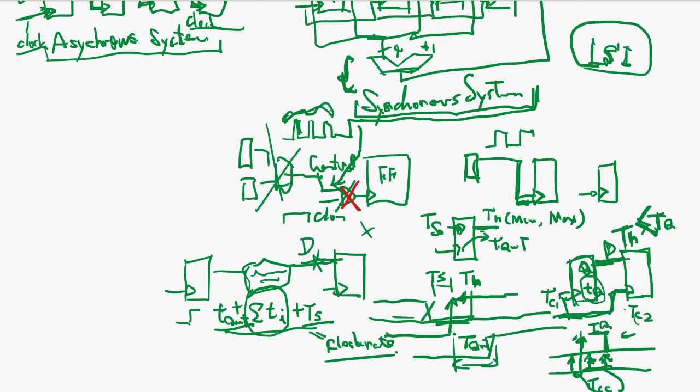If there is a clock timing skew, it may violate the setup time or hold time. In this kind of case, you want to have some kind of artificial delay, so you can insert some logic in order to make sure it satisfies all the conditions. Okay, so you have this kind of logic. You have to be careful when a flip-flop output directly goes to the next flip-flop data. Make sure to check hold time and setup, and think about the clock skew. Some percentage of clock is faster or slower, and if there is a chance for violating,